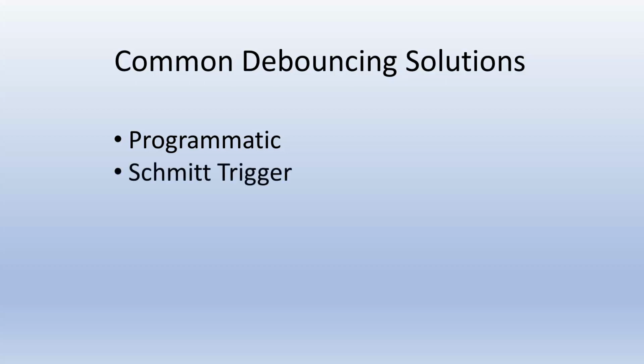If your circuit does not contain a processor and does not require complete mitigation, a simple solution such as running the signal through a Schmitt trigger may be enough to reduce the side effect of ringing. Although this may not remove all bouncing, this may satisfy a use case such as an on-off toggle button, where occasionally pushing the button multiple times to put the circuit in the correct state is acceptable.